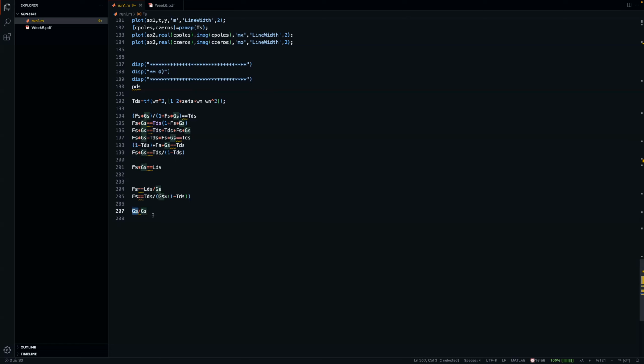So this is basically pole zero cancellation at its best, because everything is getting rid of everything. All poles are canceling the zeros, all zeros are canceling the poles of the system. So the whole system vanishes. It's a part of the controller. And then you'll add some extra stuff so that the closed loop is as desired. So yeah, and it is quite easy to design such a controller.